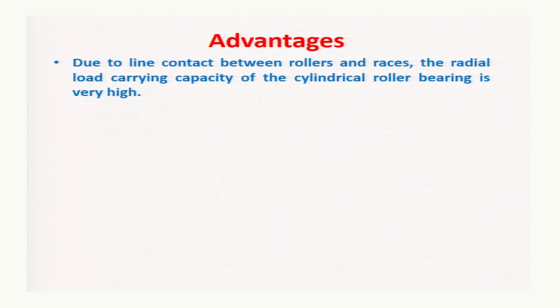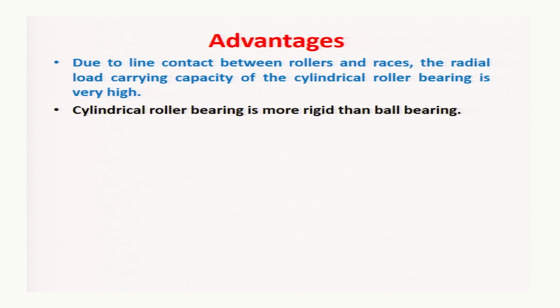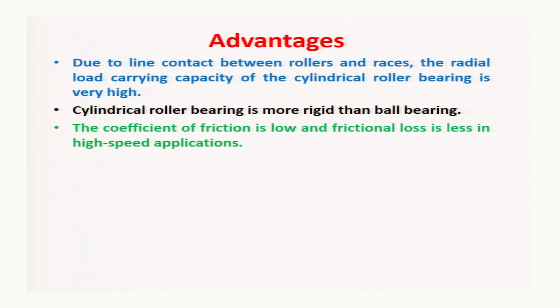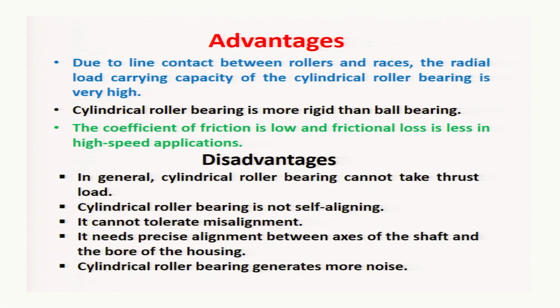Advantages of roller bearing is, due to line contact between rollers and races, the radial load carrying capacity of cylindrical roller bearing is very high. Cylindrical roller bearing is more rigid than ball bearing. The coefficient of friction is low and frictional loss is less in high speed applications.